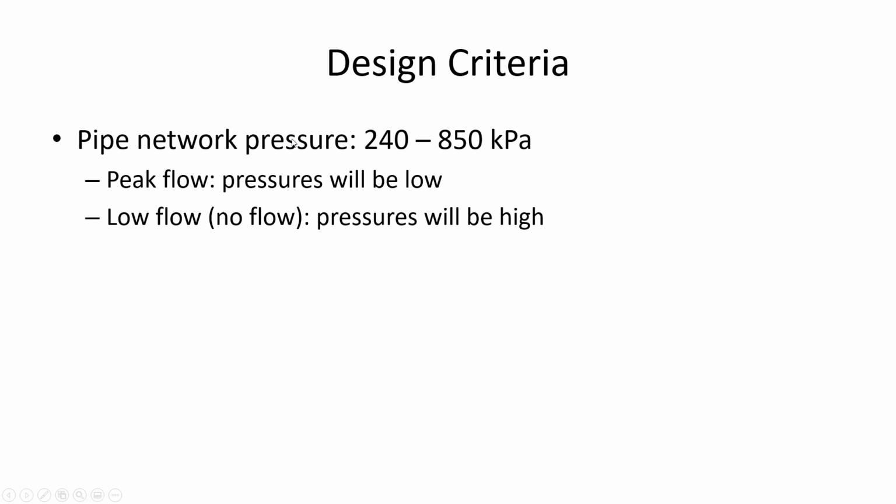And you're going to need to make two different maps for phase 2. You're going to make a map of what your network looks like under the design condition. And under the design condition, the pressures are going to be relatively low at each of those junctions. You want to get them as close to 240 as you can. Because if you make it so that your pipes are sized such that the pressure at each of the junctions is like 500 kilopascals, it's like you haven't optimized enough. You're leaving the pipes too big because you can get lower than that. The allowable range is down to 240, so your objective is to keep making pipes smaller and smaller until as many of your junctions as possible are close to this lower limit.